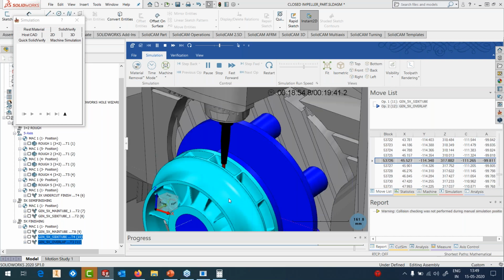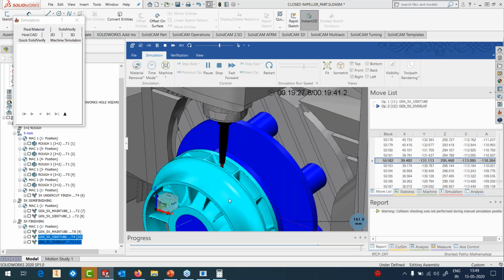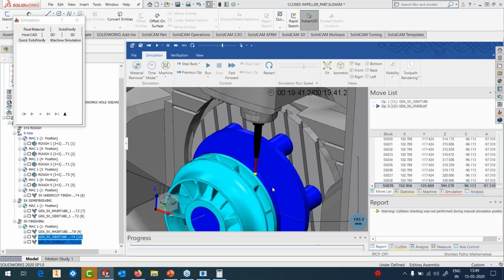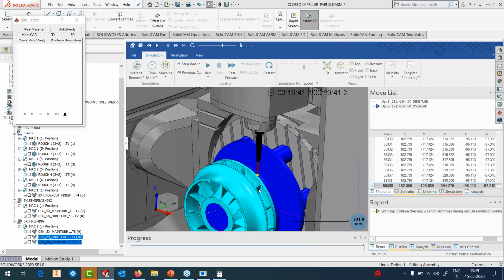Now it's actually doing the merging fillets between those two areas. So it's quite a steep fillet that we have, and that's how it machines the fillet. So no collisions, nothing. Straight away, the toolpath comes up. Again, this was a part of our template.